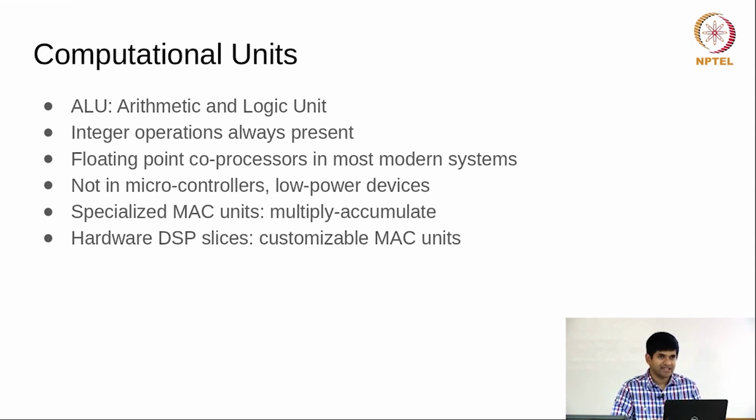Computational units, typically there are specialized multiply accumulate units that are often found, especially for signal processing applications. And in terms of the FPGAs, we come across a concept of something called a DSP slice. They are called DSP slices because the primary use of those slices is to implement multiply accumulate units. But in general, you can think of them as some hardware unit that is capable of doing multiplication.